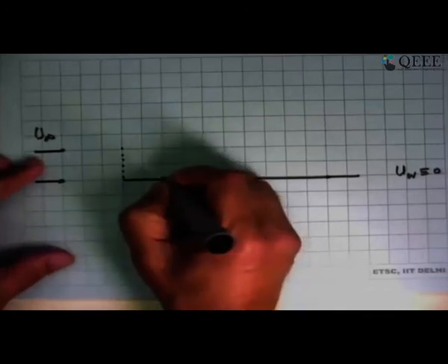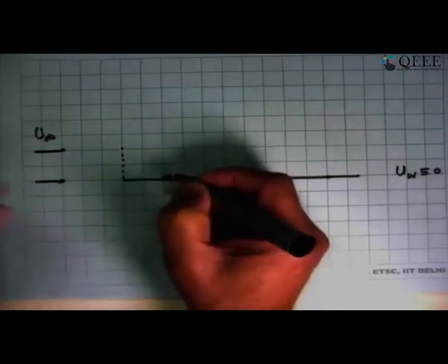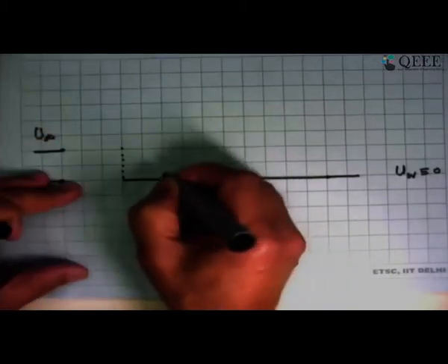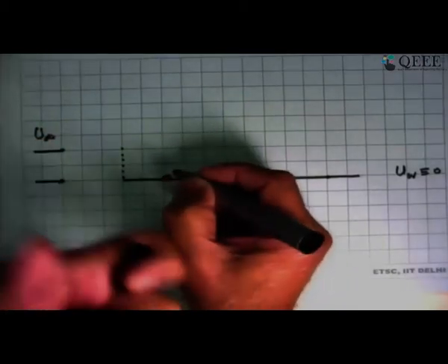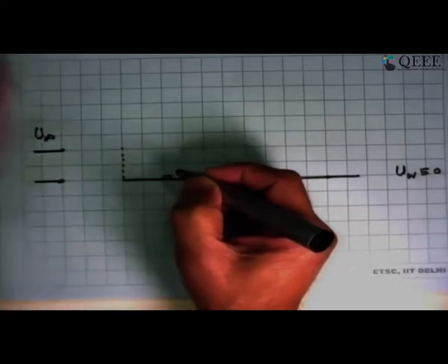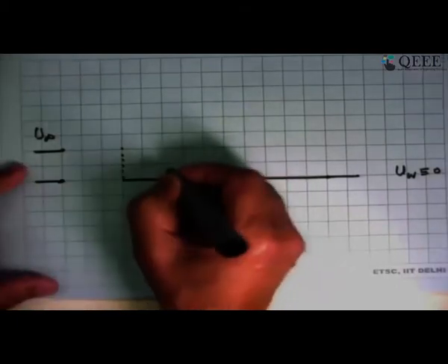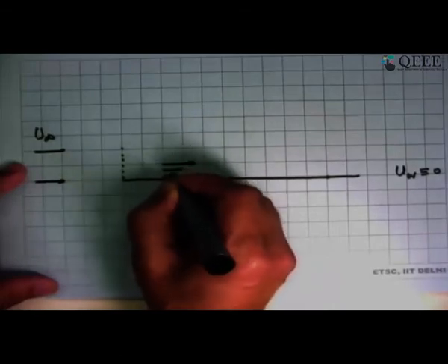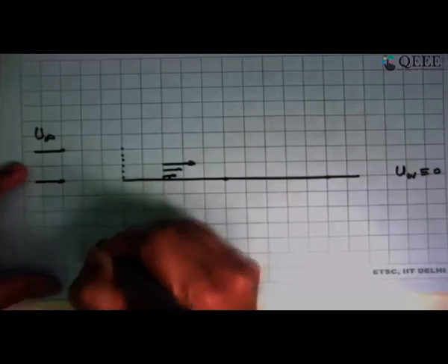A little away, this element, fluid element, is stuck to the wall, and the other elements are going past it, but because it experiences a drag, it cannot go as fast as u infinity. So here you had u infinity, but here you have less velocity, and here you have even less velocity. And I'm only drawing the u component. Further away, everywhere it is the same velocity, which is u infinity.